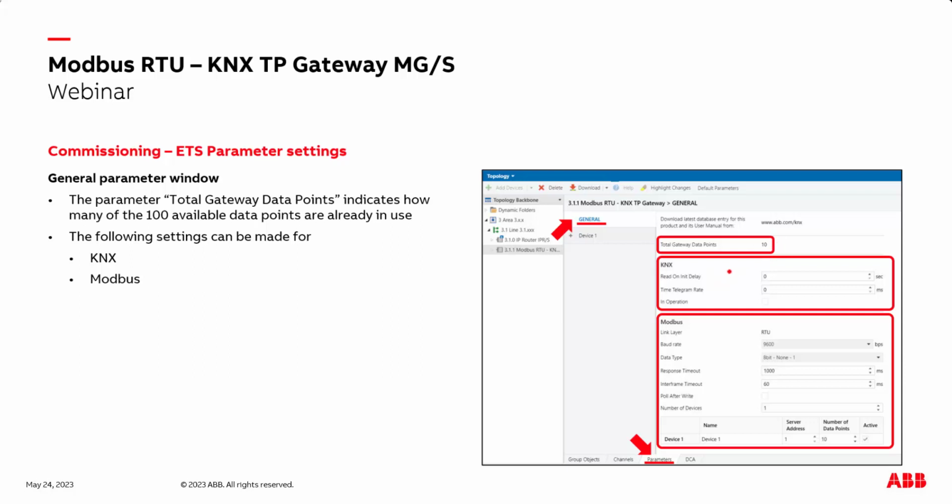If the device restarts, maybe because there was some KNX failure in the line, and the initialization flag is set on a communication object, it sends a group value read telegram to other KNX devices to read out the status and to get back a group value write answer telegram.